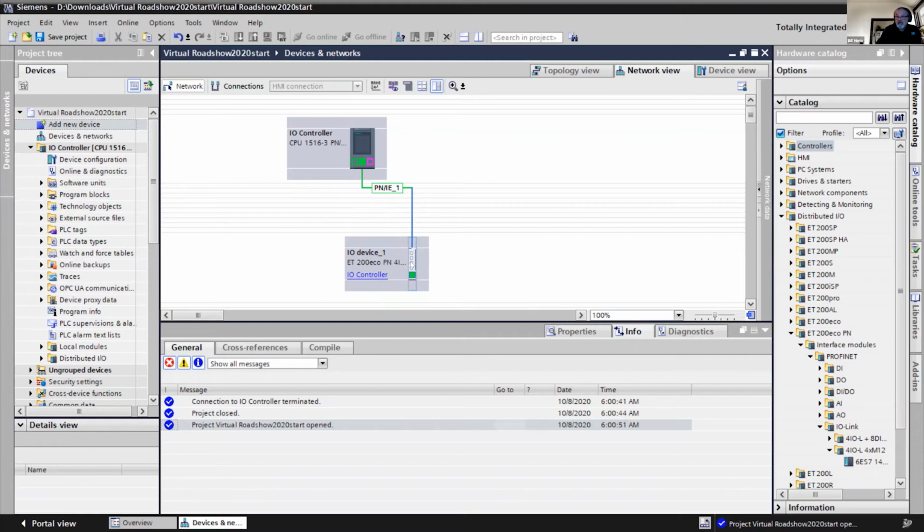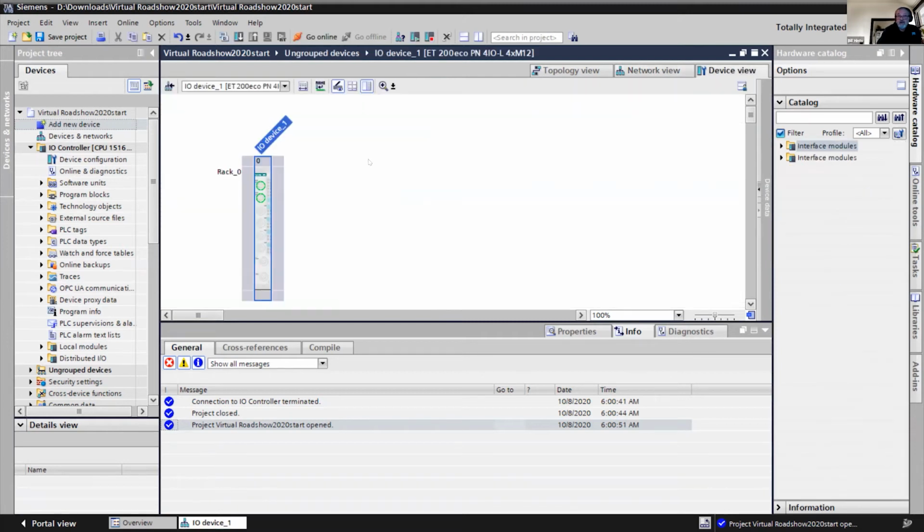Now, if I double click on my little guy here, we see that we've got several ports. These are all M12 connectors. So this is an enclosure-less device. We might want to use this on a conveyor and so forth, where we don't want to have to have an enclosure. We're just going to mount several of these devices along a conveyor or on a large machine over Profinet, and then at every one of these nodes, I would have 4 IO link module ports.